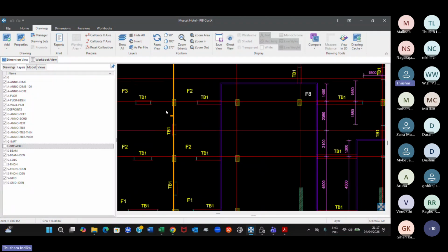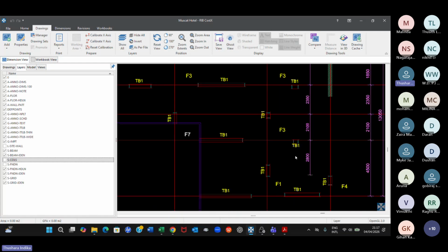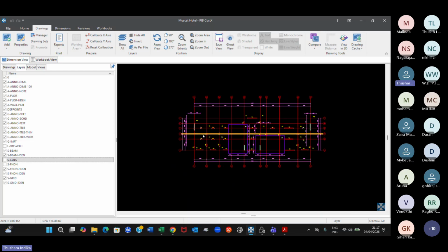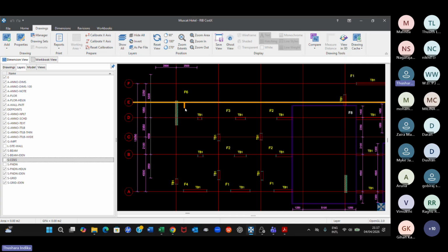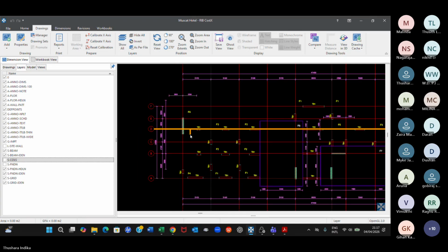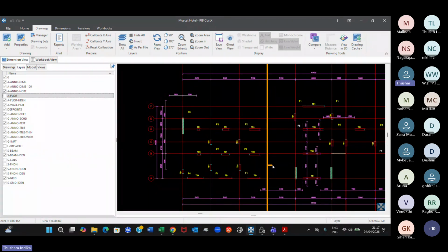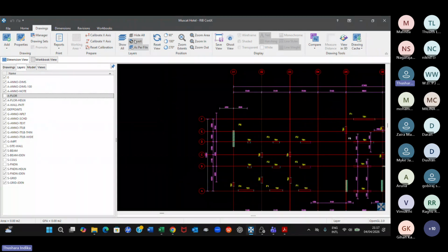If you don't select columns in one go, you have to select another column. Now I have selected all the columns you see, right? Because sometimes AutoCAD makes some issues. So you select all the columns here, and you have selected the foundations. Fine. And what is important is this labeling also, right? So I can't select the labels right now, but I do invert first.